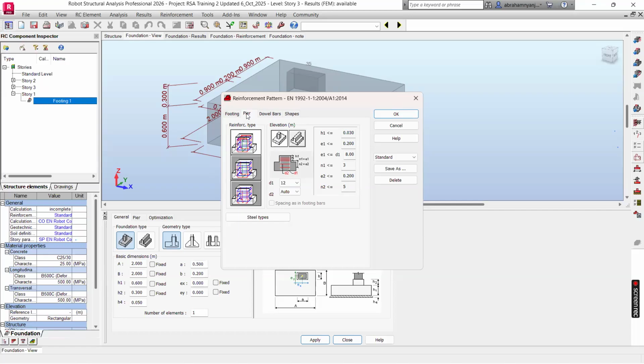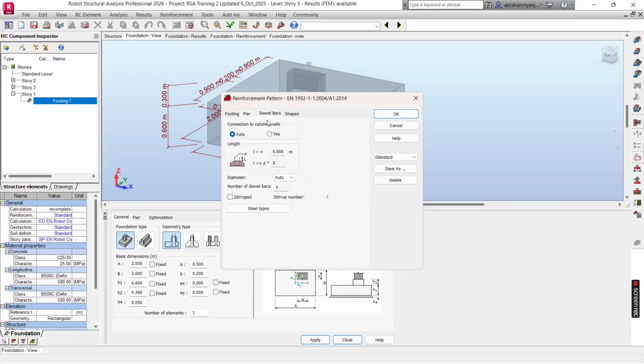If you have reinforcement that is changing on every story, it is okay, it can change if the contractor can maintain it. If you're not sure about the contractor, then you can maintain the same reinforcement from story one up to story two, though you would have over-designed. But yeah, there are those practices in the field.